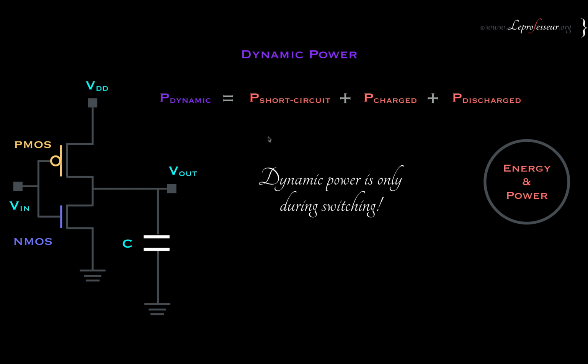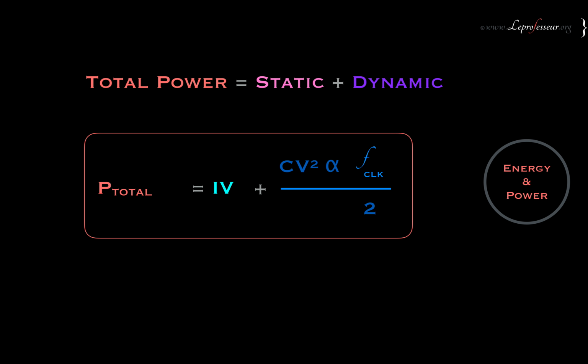It's important to have a good test case or test vectors which can exercise most of the data signals, control signals, or static signals in your chip, or in your block, whatever you are running power analysis on. Good. Just a recap: total power is static plus dynamic.